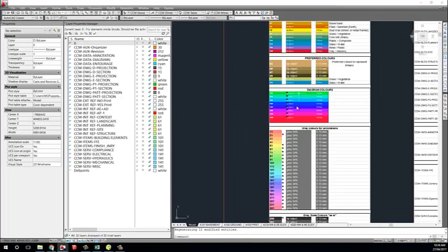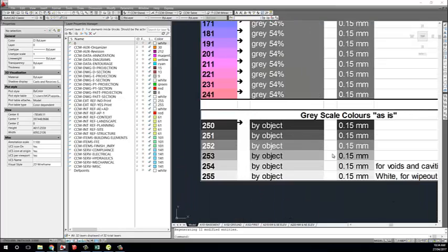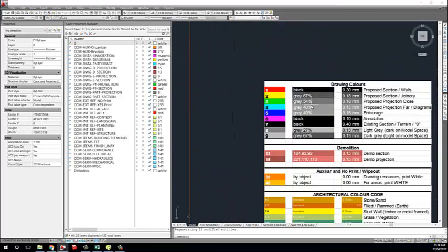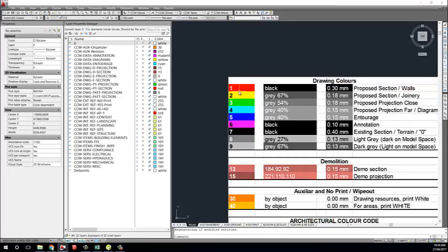Then some for diagrams, these translate and print into gray, and the grayscale is as per its color. The important ones are colors 1, 2, 3, 4, 5, which go from the darkest and thickest to 5, which is the lightest. Then 6 will be black but thin for annotation. 7 will be black, so that's the actual thick. It's very thick. 8 and 9 print.